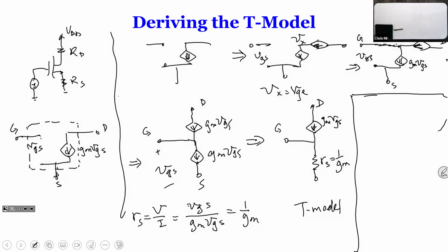Often what students get wrong in the beginning is that they look at VGS and say Vin is VGS, but that's not true anymore, because VGS is between G and S, while Vin is between the gate and ground. So there's a voltage drop over here. That's very important to distinguish, right? If we have a T model, it could make it simpler. Let's see if that actually happens. Okay, so again, we're going to take the MOSFET out and draw the equivalent circuit of the MOSFET first.